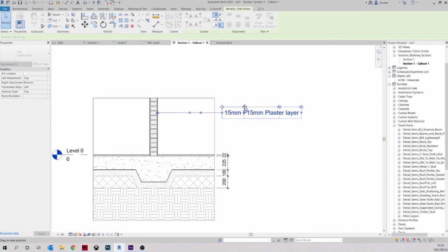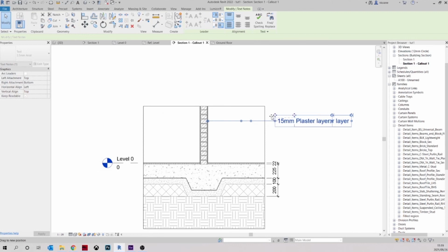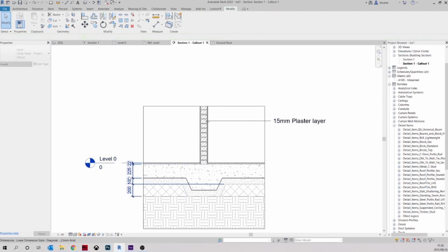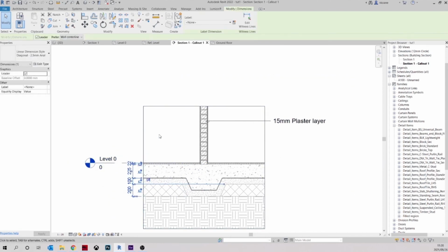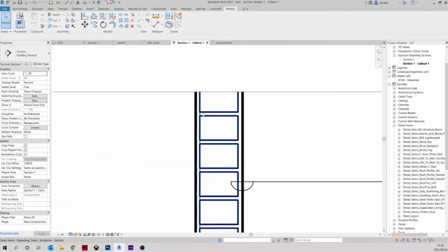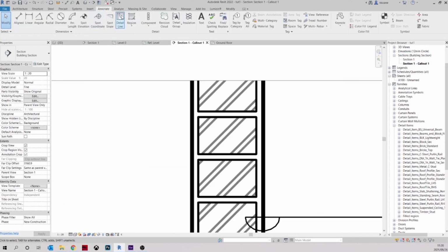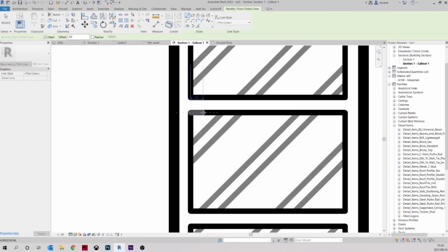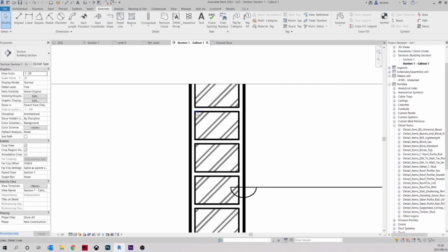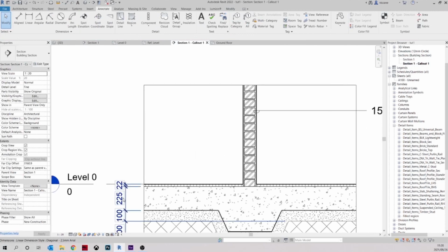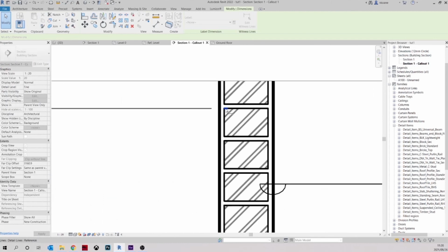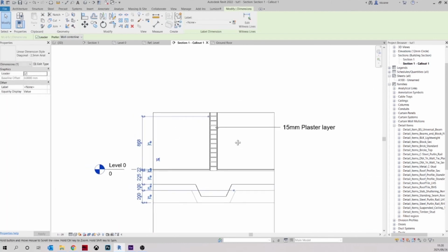and you will put it in a way that you best want for your project, or you can move it to the other side and have your dimensions like that. Sometimes, to cheat the system, I just come to Annotate and I create a line, let's say a thin line there, which you won't see, and I select the dimension, edit witness line, and I come, it will snap to that line that I have made.